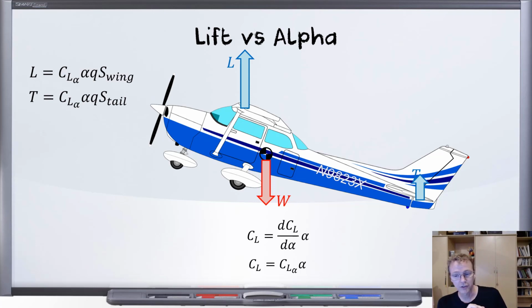There are some details that I've blown off. Some of them are very small little details, and some of them are actually kind of big details. One of those details that I want to comment on is I've assumed that the angle of attack of the tail is the same as the angle of attack of the wing here, and that's a stretch. Not even getting into the downwash effect. I'm just blowing off the downwash effect for this audience, but we'll come back to this and we'll see that actually it will probably not be the same.